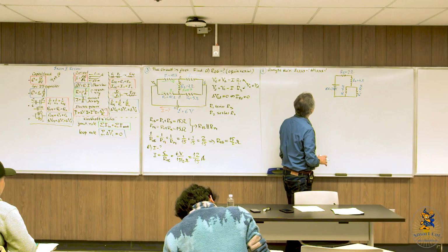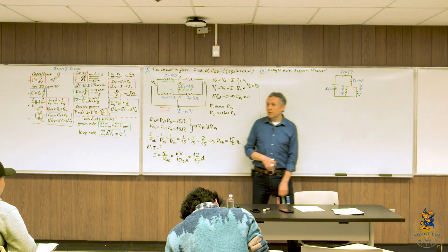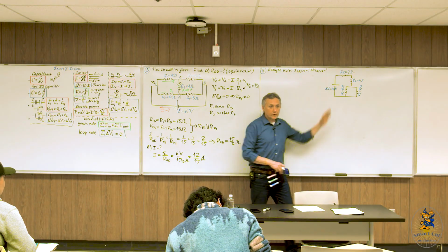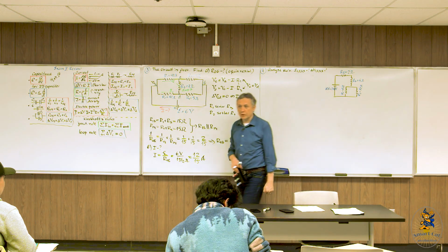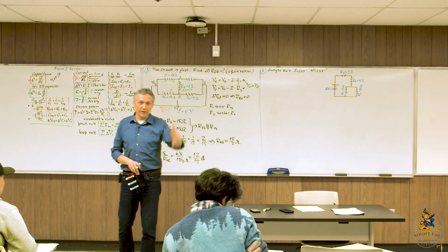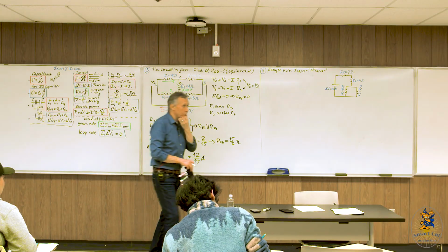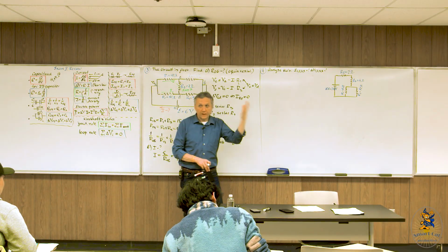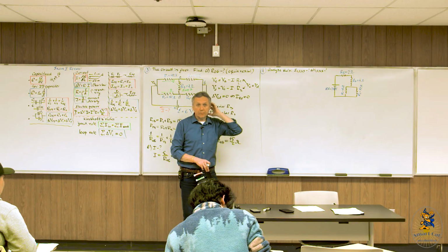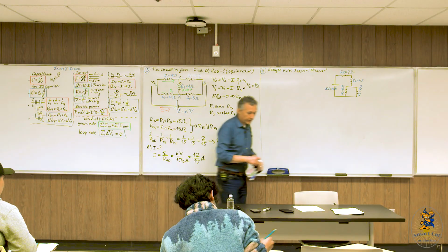So I think we have everything. Yeah. So you remember the procedure. First you need to simplify this circuit to the simplest possible, where you have just one equivalent resistor across the battery. Then you start moving back, finding what needs to be found.